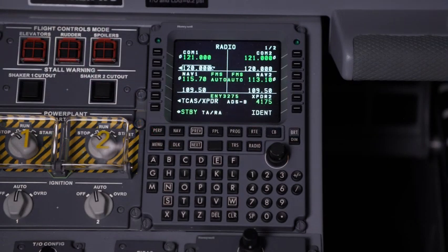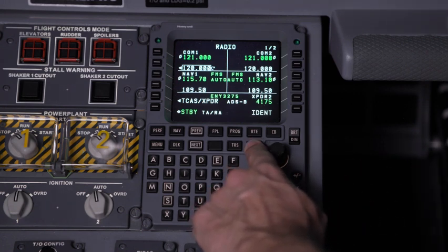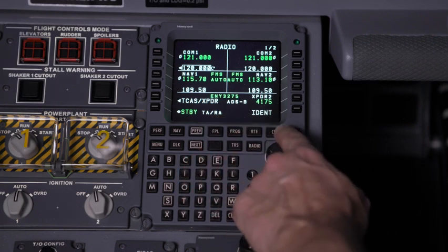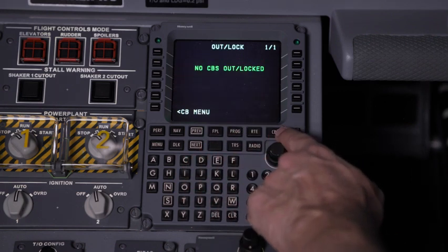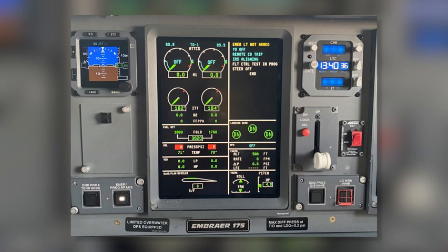Remote circuit breaker trip. The flight crew can visually monitor remote circuit breakers located inside the electronics bays through the MCDU CB page by pressing the CB function key on the MCDU. When remote thermal or electronic circuit breaker is tripped, remote circuit breaker trip advisory message is displayed in the ICAS.